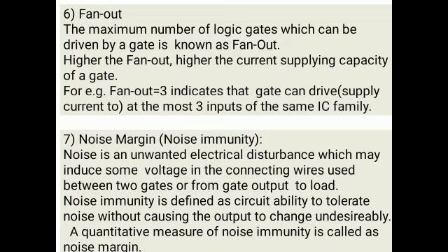So this noise, it is unwanted electrical disturbance which may induce some voltage in the wires used between the 2 gates or from the gate output to the load. So we know that we will be using the wires for connecting the input, connecting the output to the load. So there will be some voltage induced in these wires due to this noise.